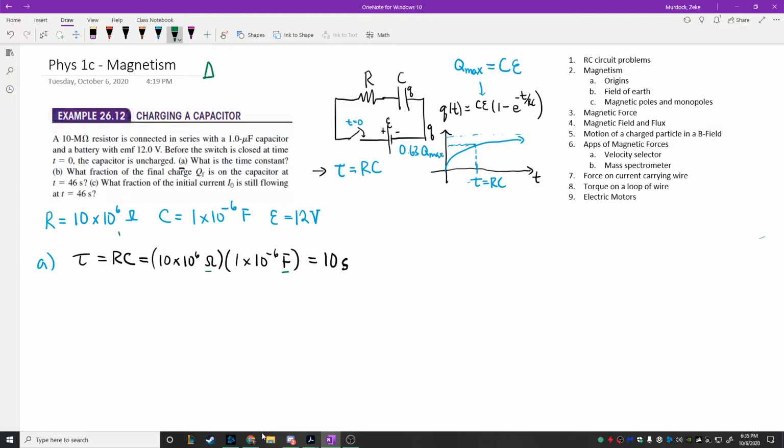So to get ohms, we know that delta V is equal to I times R, right? So you can divide the I over here to say that for the units of this right here, an ohm is going to be volts over amps. And we're multiplying that by a farad. Farad comes from this piece right here, so it's a coulomb divided by a joule.